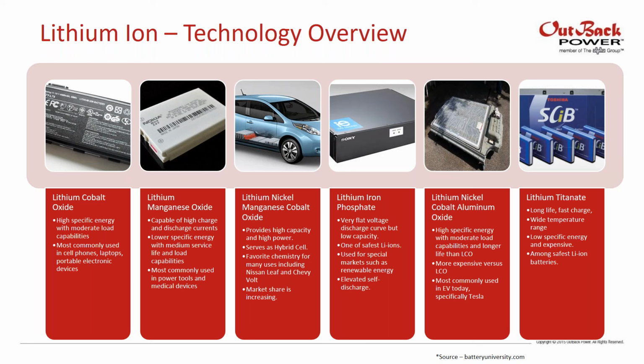However, they do have really specific charge parameters. So depends on your definition of maintenance. You don't have to add water, but you have to be really careful how you charge them since they're not tolerant to overcharging whatsoever.